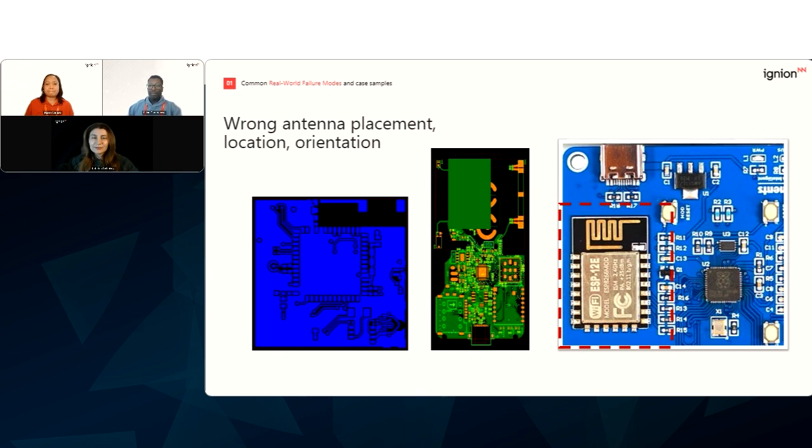It's a lot easier in that way to fix any other problems you could have as far as performance is concerned, because the antenna is a sensitive device, right? So anything that surrounds it impacts its performance. If you look at the picture, the most obvious one is the one on the right. So here, you've got an antenna integrated on a module. And on top of that, it's sitting on top of a motherboard. And obviously there's not enough clearance for that antenna. So it's sitting on a ground plane essentially. And that's a huge capacitance that's going to kill your antenna radiation immediately.